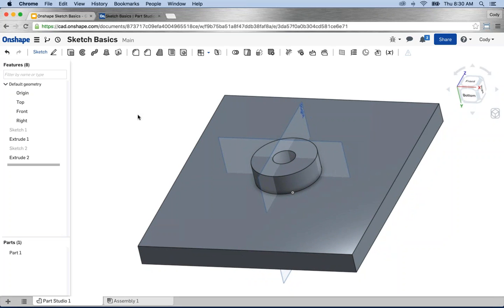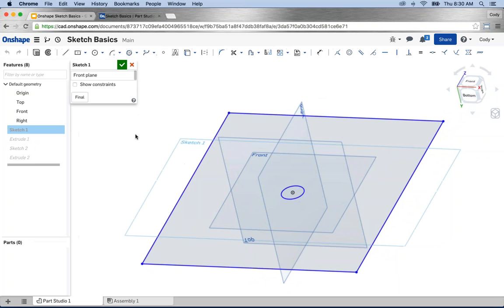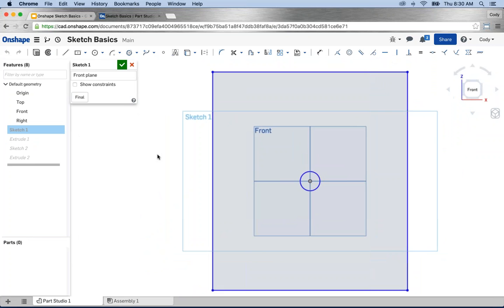If you decide later on, let's say months down the road, to change this circle, I'm going to jump back, and let's say I change the diameter of this inner circle to something bigger like that. If I dimensioned it in two different places, I now have to go back to two different places to change the diameter.